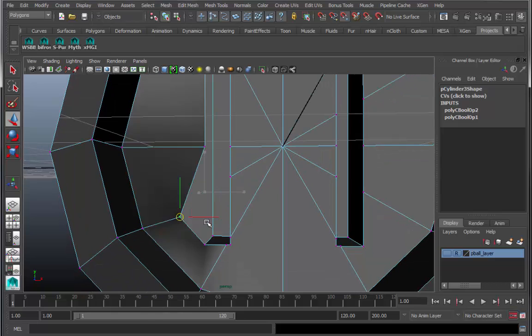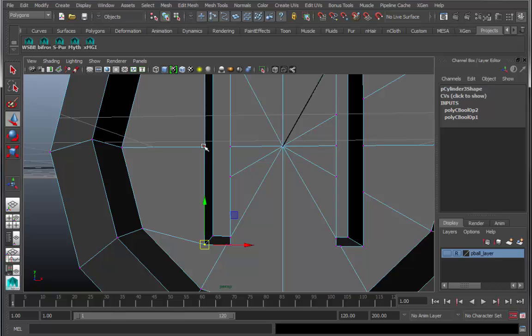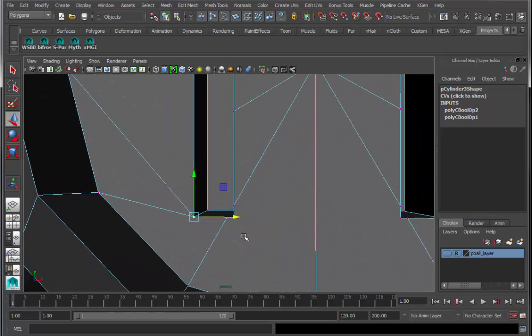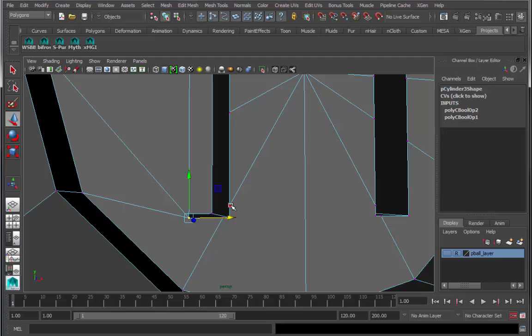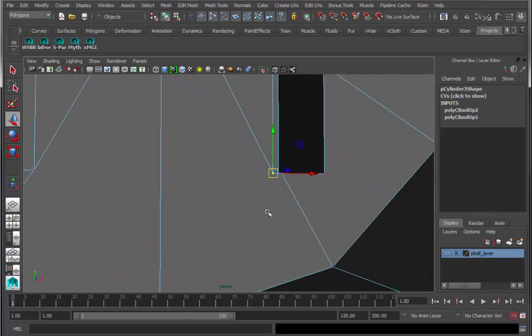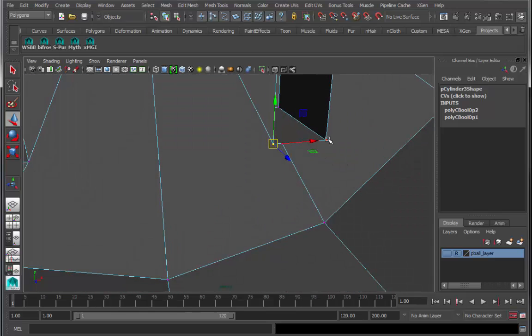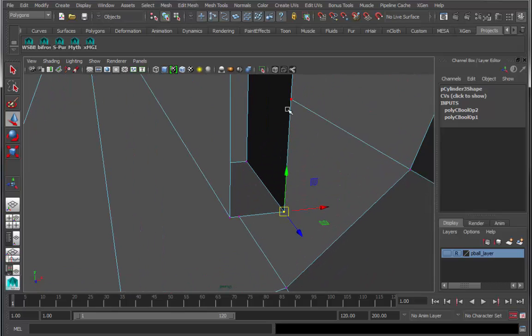So what I'm doing now is I'm just snapping all the geometry to its nearest corner. And that's going to help me when I finally do my merge of all these little vertices. They will be welded onto each other, and it will keep the surface clean. So I don't have all this strange double and triple vertices in the geometry that necessitate a lot more faces being drawn than we actually care to have.